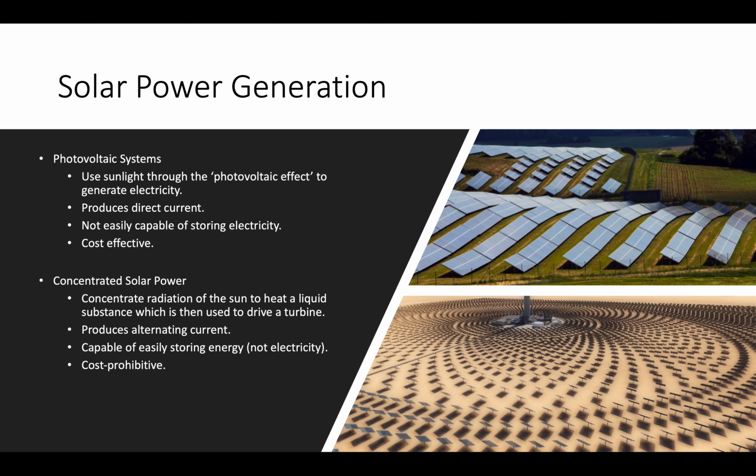PV systems, I would say, constitute a bit more of a proven technology, however, because they can be built easier, at lower cost, and in a much shorter time than CSP plants. And CSP plants also require a lot of land. Moreover, PV panels also have a demonstrated and substantial price drop, and that economic efficiency that's been found over the last 10 years with photovoltaic cells hasn't been matched with CSP plants. I think between 2009 and 2017, photovoltaic cells' levelized cost of electricity has dropped about 76%. That efficiency gain has not been found with CSP.